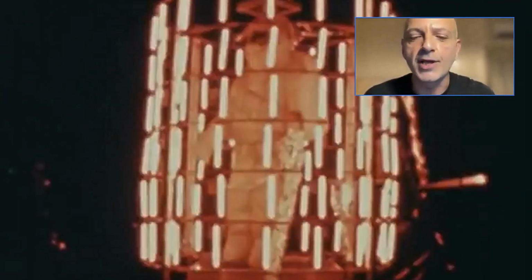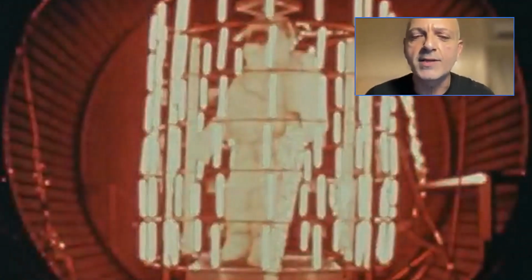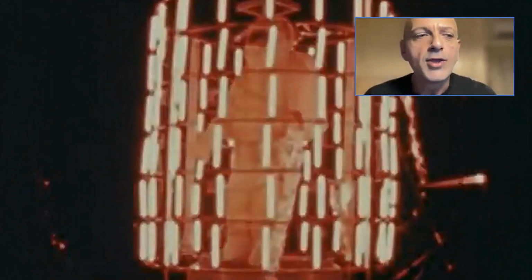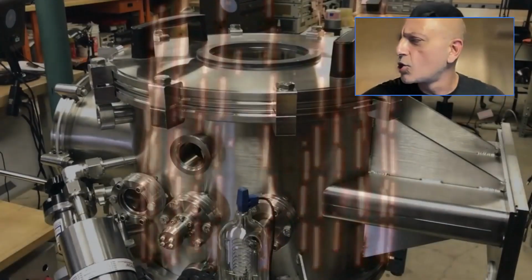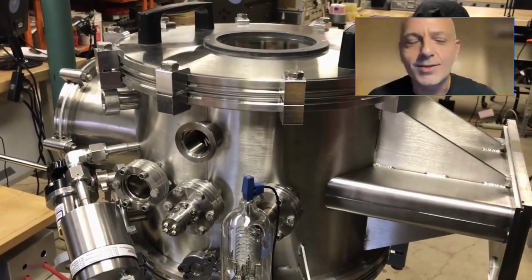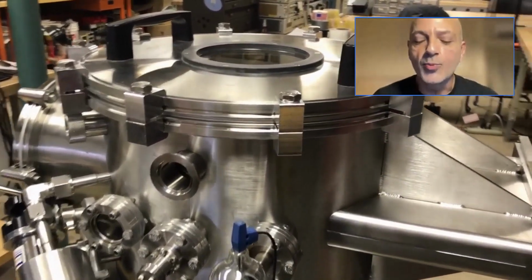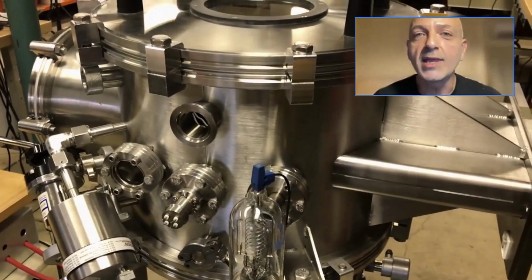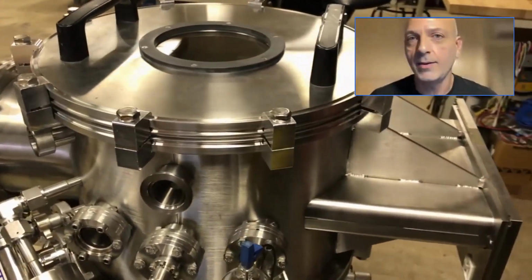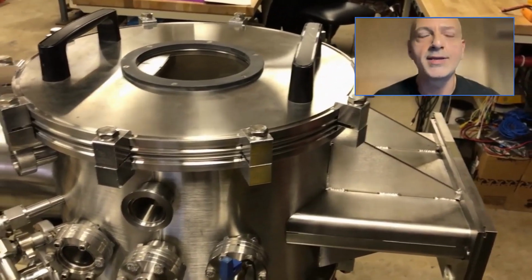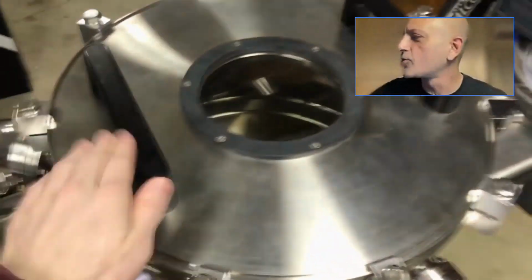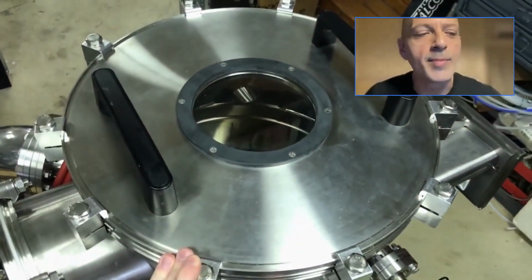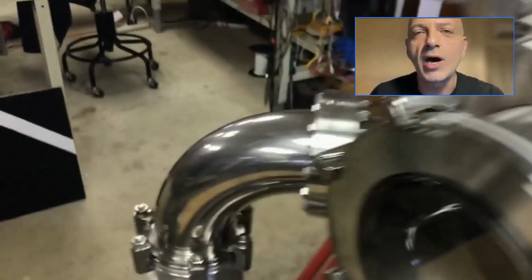Now, if you raise something, and you raise its temperature and you bring it up to 70, 80, 90, you greatly increase everything, all the processes. So if we are to be very harsh, not only we should put it in a vacuum, but we should heat it up as well. And that way, not only it would degas like crazy, it would be in an accelerated manner, doing that. If it were to survive, like 2 days with a bit of heat, it's going to survive 2 hours.